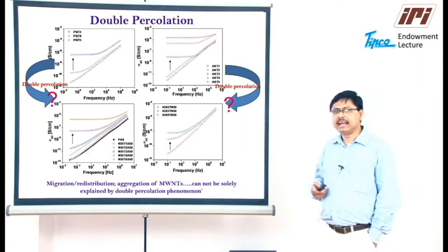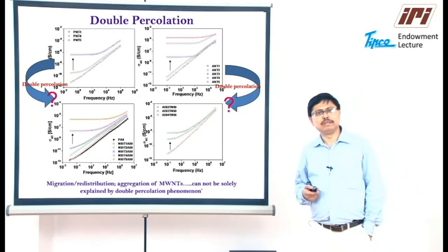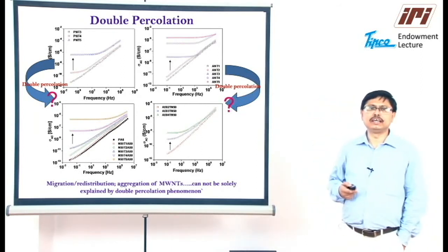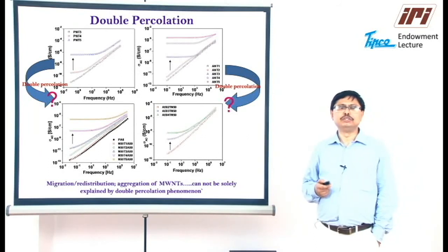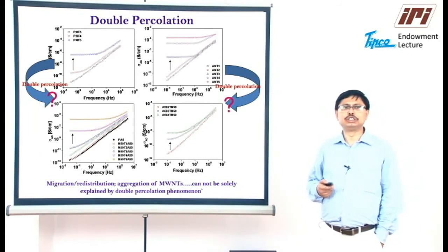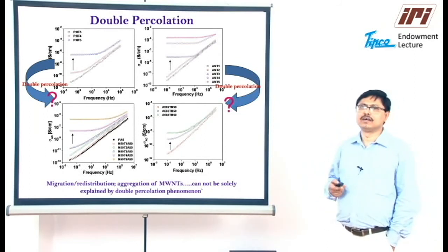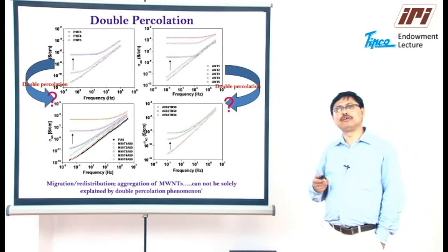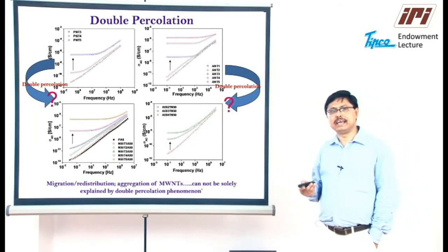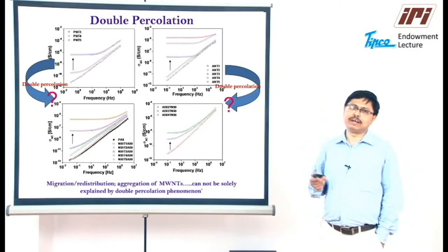Now, one can carry out this melt mixing inside the twin screw, conical twin screw microcompounder using a different protocol, a two-step mixing process where polyamide 6 is mixed with the multi-wall carbon nanotubes for 10 minutes, followed by the addition of the ABS, and or vice versa.